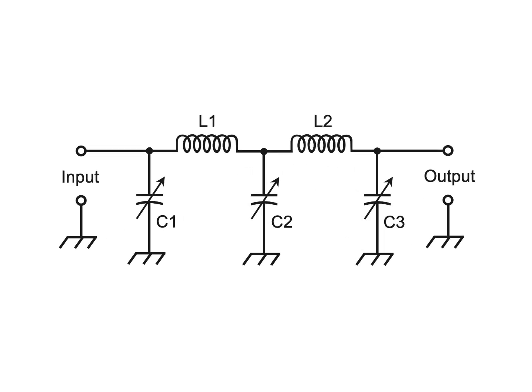This shows a circuit that's a little more complicated than the previous ones, but in a certain sense, contains both of them put together. When we follow a Pi network with an L network, we get a so-called Pi-L network. The advantage of a circuit like this one, compared to those in the previous two diagrams, lies in its ability to make radio transmitters work with antennas that would otherwise not accept power very well. Those two extra components can go a long way.